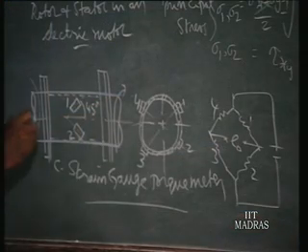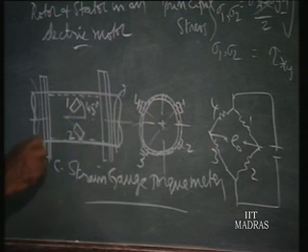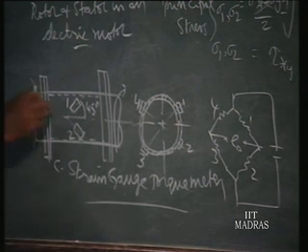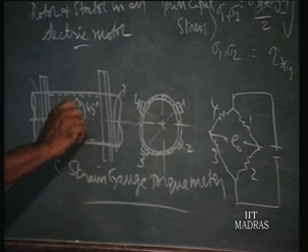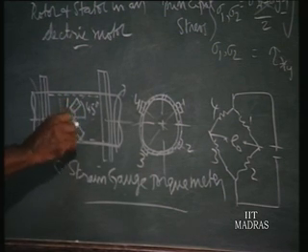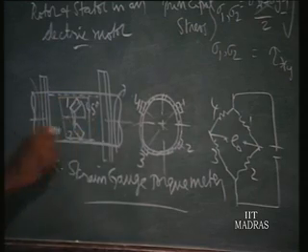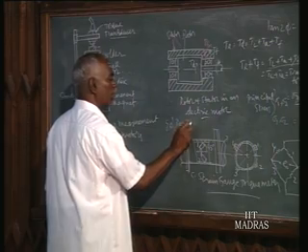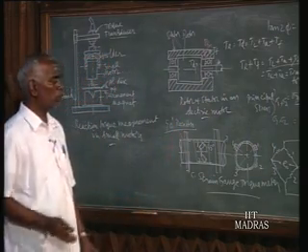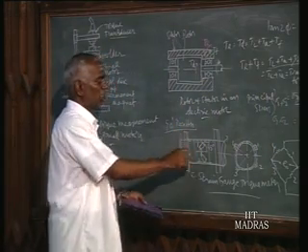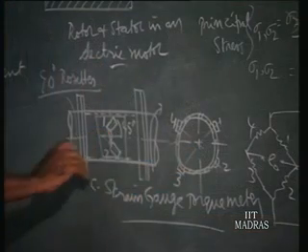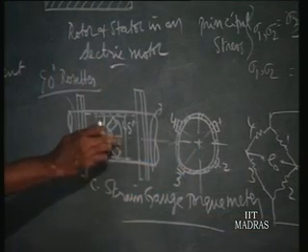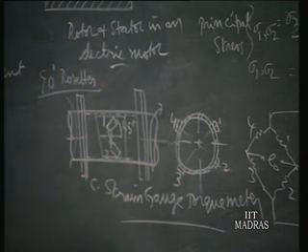In the shaft you have to mark a line, mark the axial direction, and then 45 degrees to that you have to paste 2 strain gauges, 45 degrees this way. Now you will find that from one axis to the other axis it's 90 degrees, and these 90 degree rosettes are available in the market. Strain gauge rosettes: in one mounting, the two strain gauges at 45 degrees to the central line, which is also marked there, are fixed, and they are available in the market.